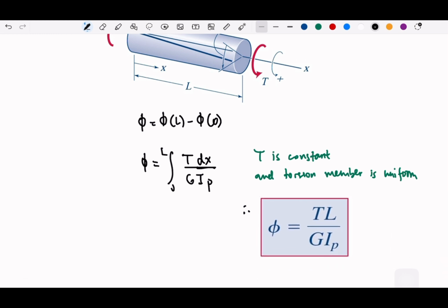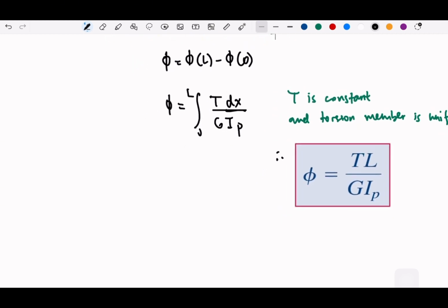The angle, and this will be, so remember, okay, I will write what you have in axial deformation: the elongation is F, L, A, E. So this pretty much works the same. The difference is the elongation part. In axial deformation, you have F, right? L, and then A, area, and then the modulus, the Young's modulus.